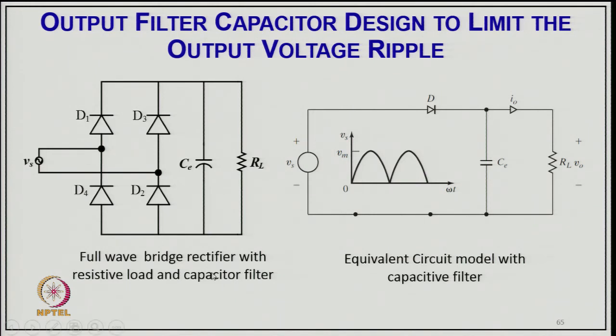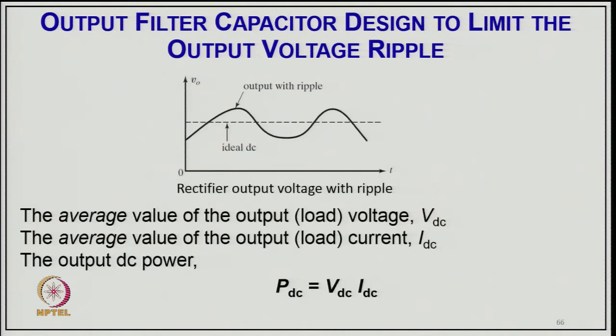and of course, we are using here a capacitor for the purpose of filtering, typically getting a better DC across the load. This can be equated here with the rectified DC of this nature, in series with the diode, and this diode will conduct only when the supply voltage is more than the capacitor voltage, and of course, the load current will be continuous because the capacitor will give the voltage. So, you will get some ripple, and the ripple will depend on the time constant of this RC circuit, otherwise this will give a good quality DC at the output,